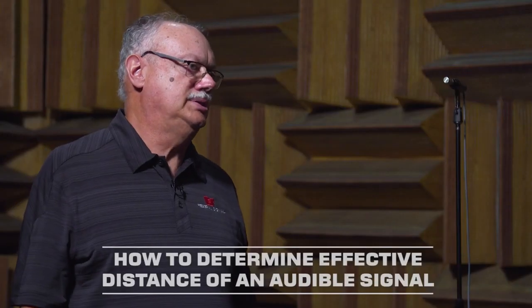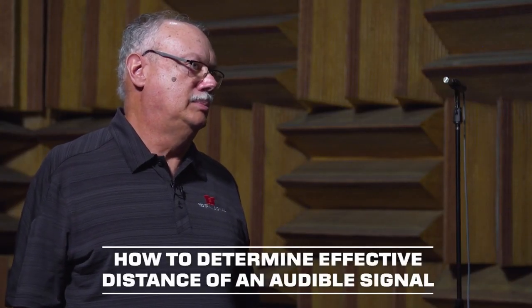So once you know your SPL, how do you calculate the effective distance of an audible signal? Okay, first you need to know the minimum SPL that you are working with. If you're making indoor measurements, you take the SPL of the speaker and drop it by 6 dB per distance double. If you're doing an outdoor measurement, you want to use 10 dB per distance double when you get greater than 1,000 feet due to air absorption.